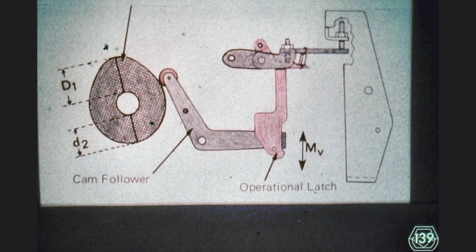As a final point, we ask you to think of the input section of the IBM Selectric Typewriter as being represented by all of the mechanisms which have to do with the horizontal front to rear movement of the selector latches, and those mechanisms which allow the engagement of the keyboard. The movement of selector latches constitutes the selection process, and the engagement of some clutch is merely a form of power tapping which the typewriter uses in order to electrically drive the selected mechanism. What happens after this point is part of the output section of the machine. Thus, you can easily see that the name Selectric is an extremely well-conceived name for this machine.